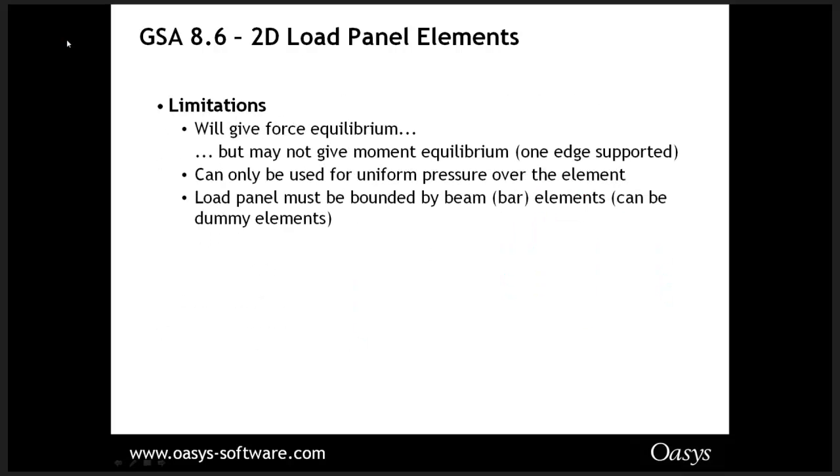Some of the limitations, well, you will get force equilibrium, but you may not have moment equilibrium. Some of the support conditions simply take all the load and put it on one edge, for instance. And in that case, you won't get complete equilibrium between your applied loads and what's actually being analyzed. So that's something to bear in mind. It's not a big issue, but it is just one of those areas where you can get some lack of equilibrium introduced in your model.